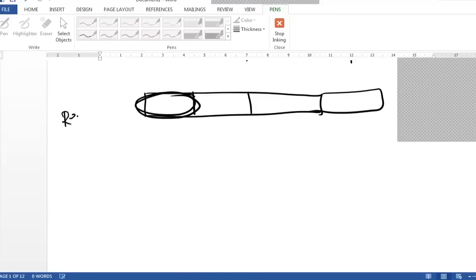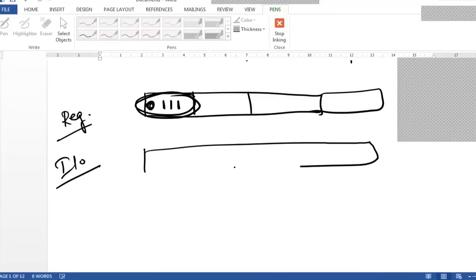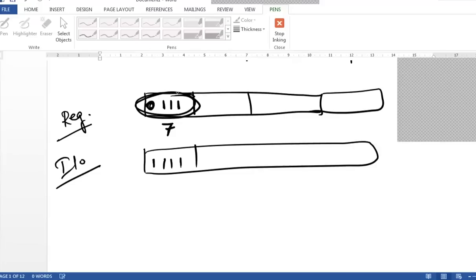For a register reference instruction, what did we say? That the first bit is 0 and the remaining 3 are 1. For input-output instructions, the first bit is 1 and the remaining 3 are 1. So if my instruction starts with 0111, it means it is a register reference instruction. The remaining bits can be anything. If it is 1111, the first bit would be 1, and so on.